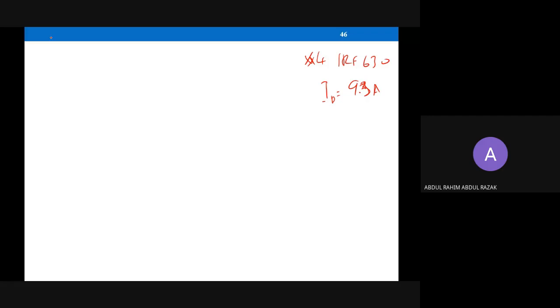So there are two basic ways that I've taught you to justify the maximum limitation of the switch. One is that you have to justify, without heatsink, how much current can be conducted through that switch. And the other is with heatsink, which involves a minimum of three elements, including how big the heatsink is.